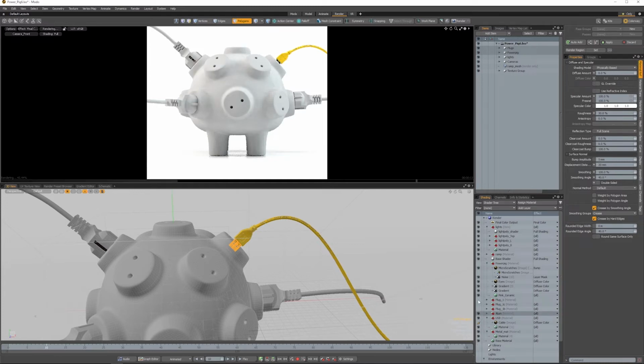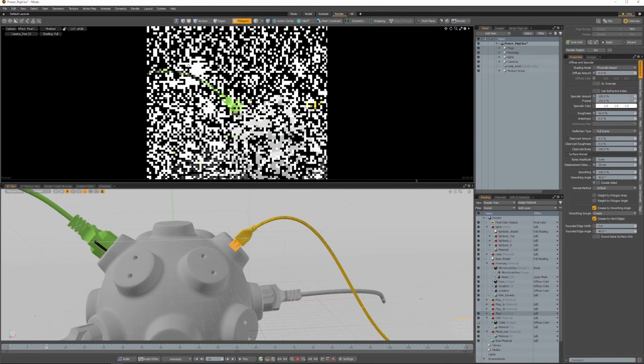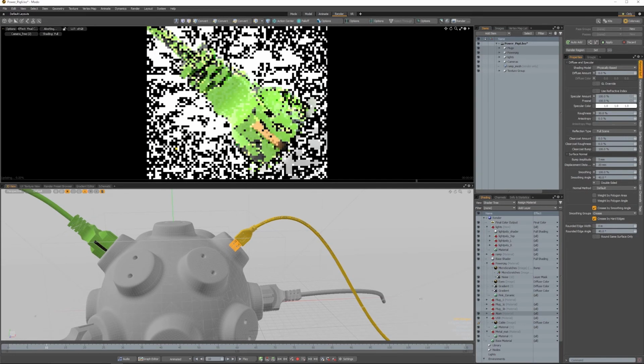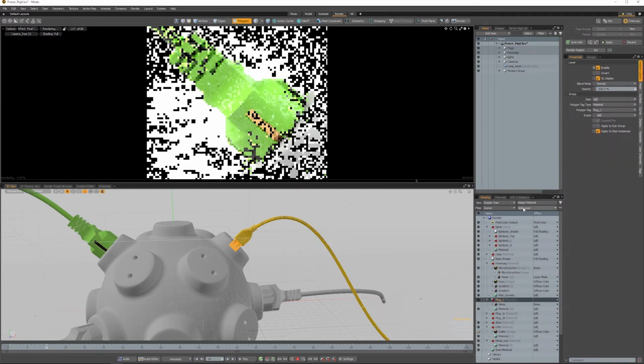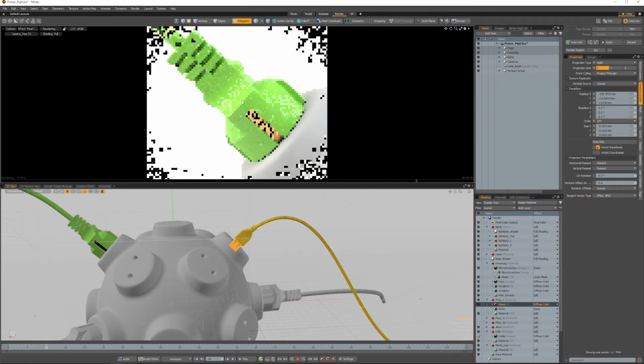And for example, let's go with the plug number 1, which is this green one, and I'll go to the free camera and zoom in to this plug to show you. Right, so if you go in, I'll just deactivate this noise and I'll create it again. So I added a texture, a procedural texture. If you come to add layer, textures, noise, I know that it comes in really big, so 33 millimeters is too big. So just double click, 1 millimeter. Okay, it's getting there. I'm seeing some noise.